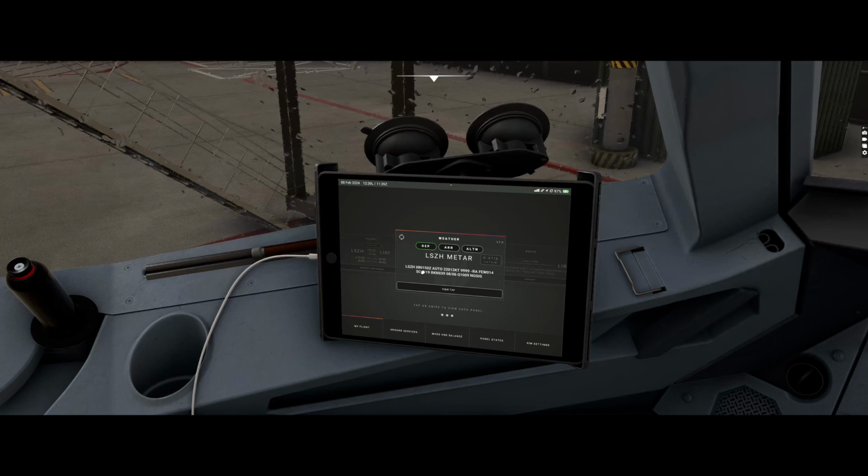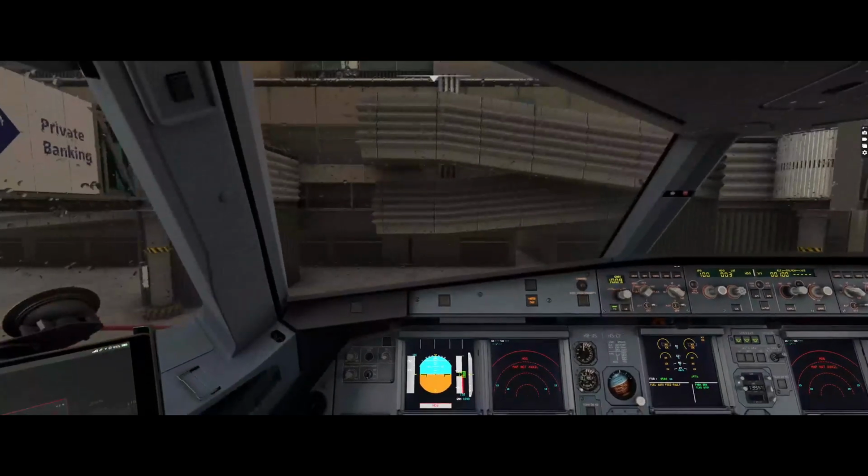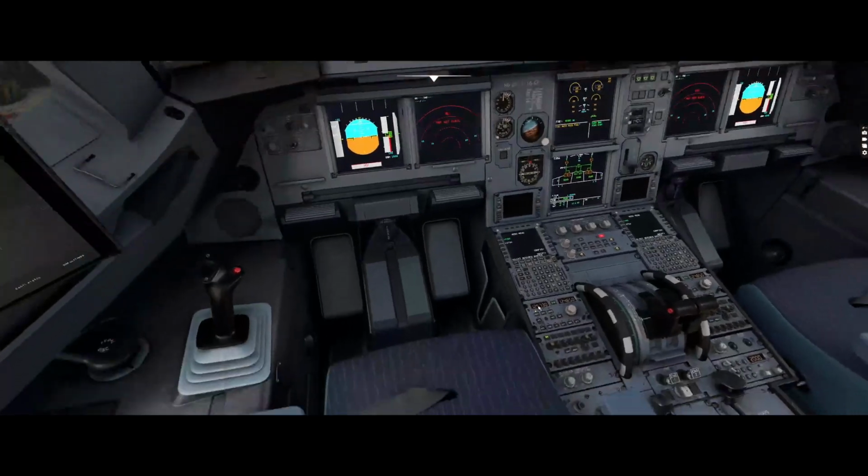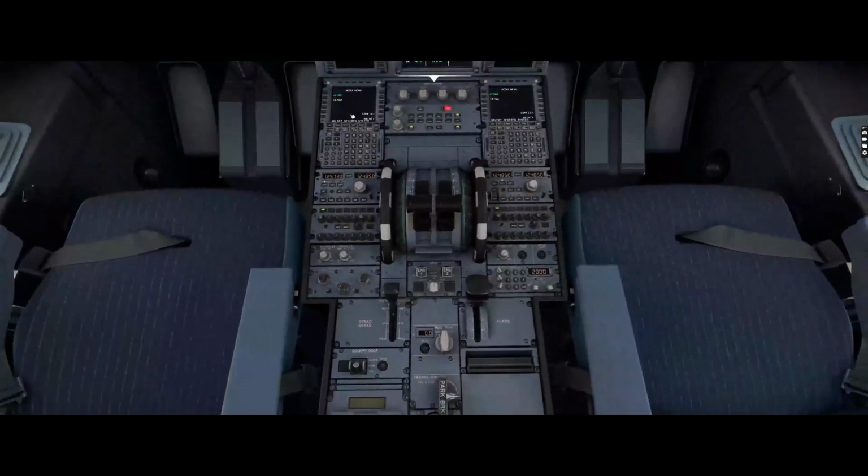So clearly here that's our time in Zulu, 220 at 12 knots. Great visibility, a bit of rain. You can see few clouds at 1,400 feet, I believe, and then scattered clouds, and then broken clouds, and then temperature is 0.8 degrees, and dew point is 6 degrees as well. So there you go, that's your METAR there. So that is set. Then we'll come ahead down, so we'll go to our radio panel.